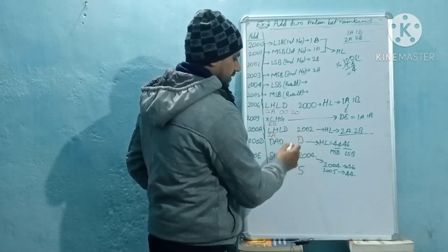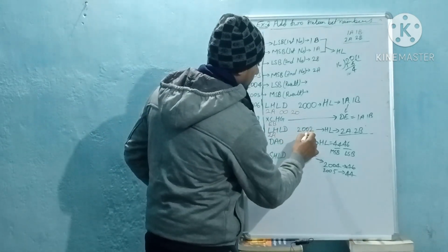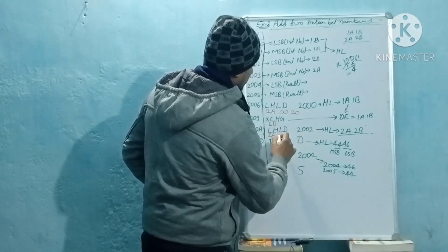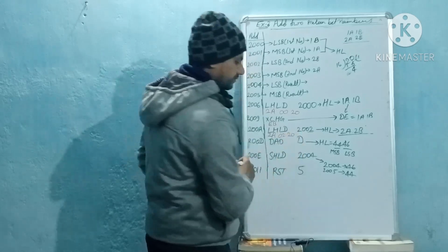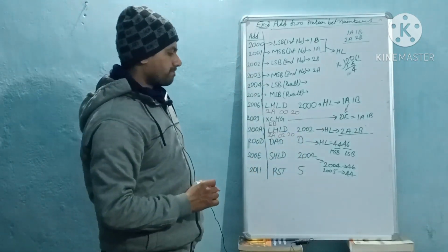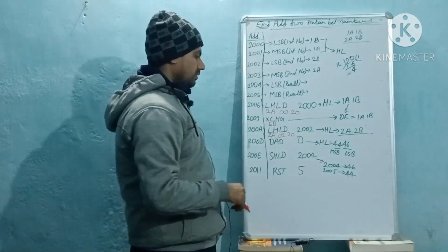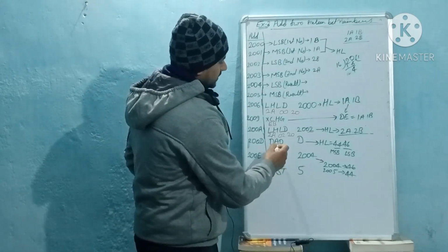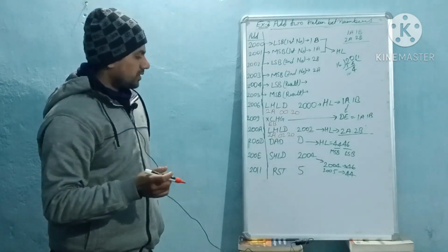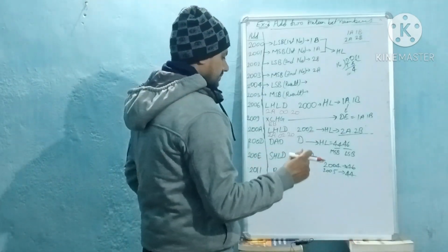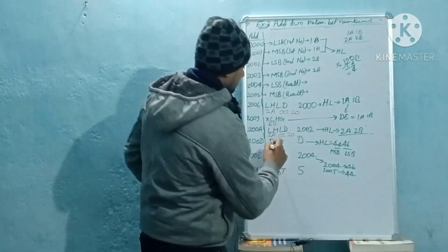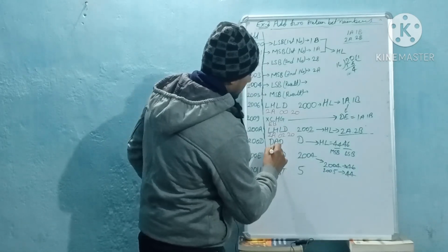So we write the LSB first, 02, then 20. Then the next instruction is DAD D. For this one we have the hex code 19.